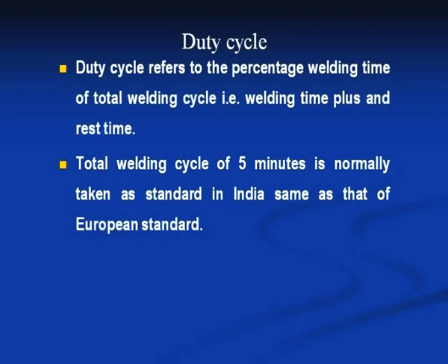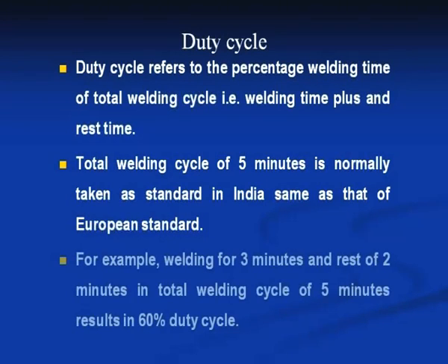The total welding cycle of 5 minutes is normally taken as a standard in India, same as that of the European standard. For example, welding for 3 minutes and a rest of 2 minutes in a total welding cycle of 5 minutes results in a 60% duty cycle.